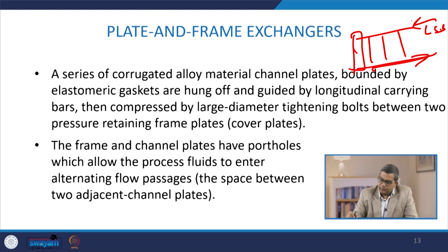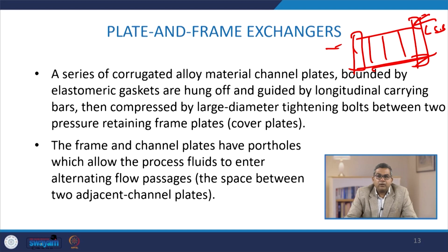Here, if you visualize that these are the two retaining frame plates, or sometimes referred to as cover plates. The frame and channel plates have port holes which allow the process fluids to enter alternating flow passages, that is the space between the two adjacent channel plates.